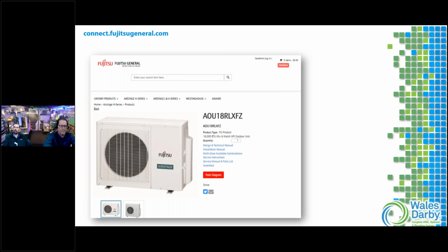Unfortunately, everything that is published in that catalog, if you have access to a paper catalog, and if not, there's a QR code we're going to talk about that gives you access to the full line catalog, you look at the back cover and some of the notes, and it'll explain where those BTU numbers come from. Those are AHRI testing numbers that they're advertising, and they might not be real for your region. Locally, where we cover in New York and New Jersey, we're looking at a 10 to 18 degree design temp.